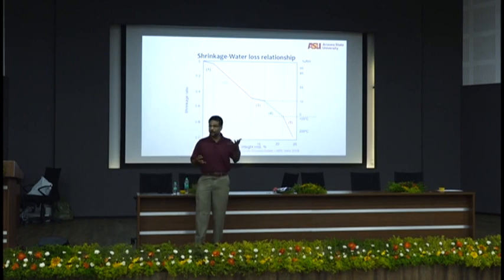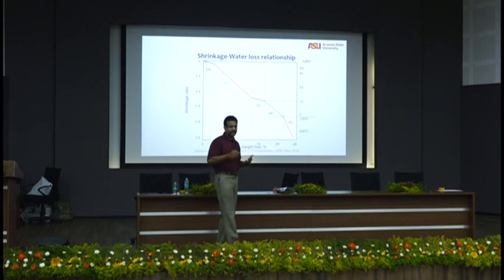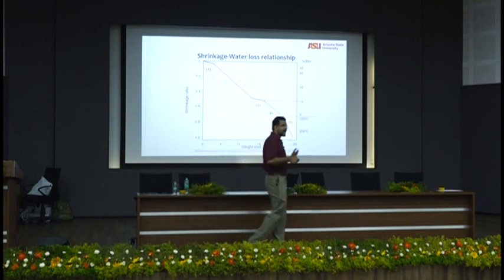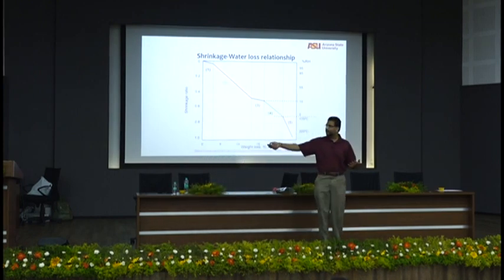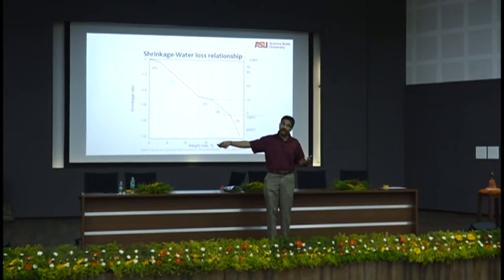Pressure is inversely proportional to the size of the pore. Therefore, for a really small pore, to eject water you need a very high pressure, or a very high stress, or a very high temperature. So you will still have a very high relative humidity. With that kind of relative humidity, it's very unlikely that these slabs will crack.